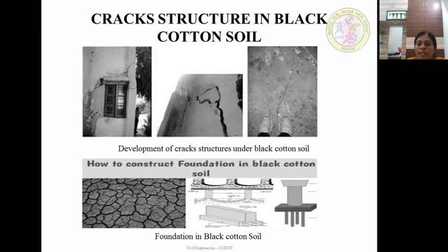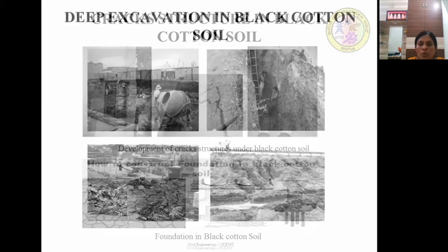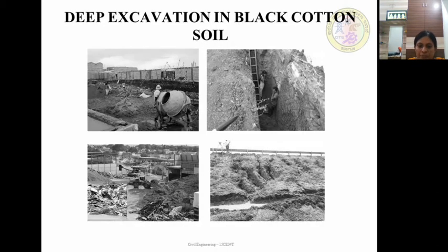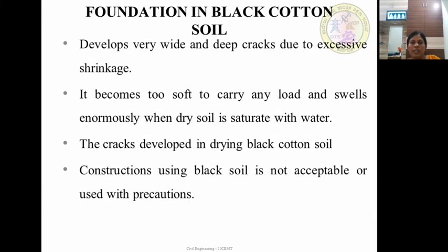The load bearing capacity of black cotton soil is very low, which causes various types of foundation failure, like punching failure and general shear failure. Next, the figure shows the deep excavation in black cotton soil and foundation in black cotton soil.